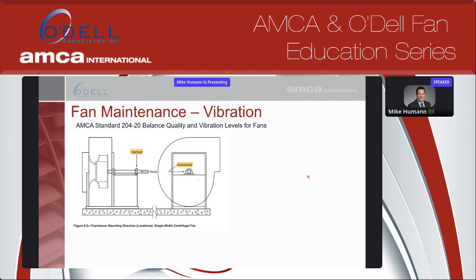And vibration is really critical, and you want to make sure your fan's in tolerance for your application, so you get the best longevity out of it. Because vibration can lead to all sorts of problems, including bearing failure. It can lead to wheel failure, and other issues and damage to your equipment. So it's really good to have a baseline reading once that fan's installed, after it comes balanced from the manufacturer, just to make sure it's where you want it. It doesn't need to be further balanced due to the install.